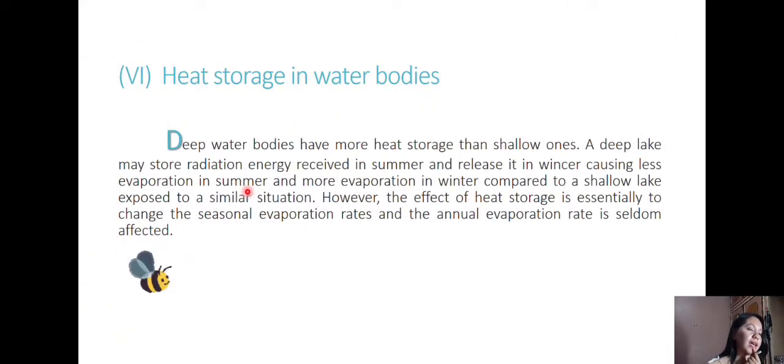Lastly, heat storage in water bodies. Deep water bodies have more heat storage than shallow ones. A deep lake may store radiation energy received in summer and release it in winter, causing less evaporation in summer and more evaporation in winter compared to a shallow lake exposed to a similar situation. However, the effect of heat storage is essentially to change the seasonal evaporation rates, and the annual evaporation rate is seldom affected.